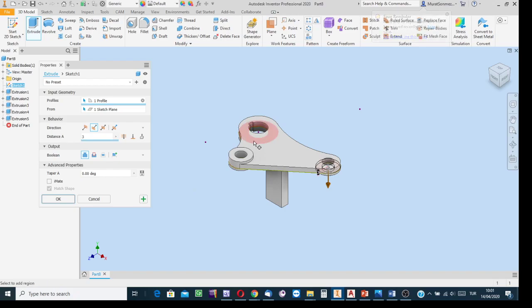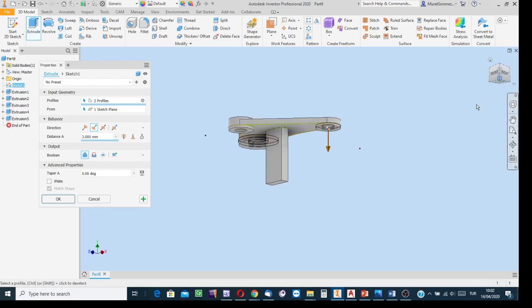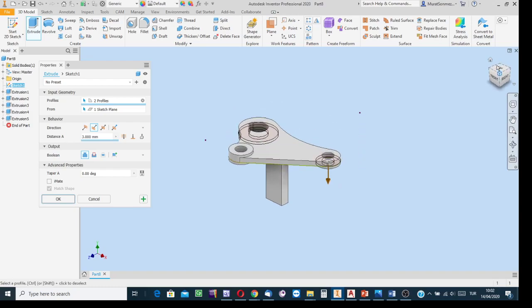Since the sketch is at the back side, relative to the sketch plane, the distance for the tip of that boss is 6 plus 6, 12. Okay, indicate this profile. Not to cut, to add. Which direction? This direction is the wrong direction. The boss is to be created in the opposite direction. So flip the direction and then into this box write 12.